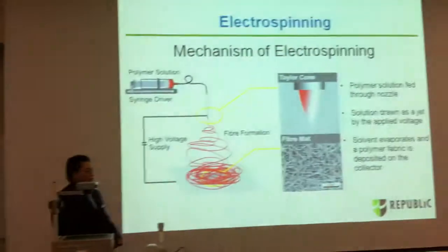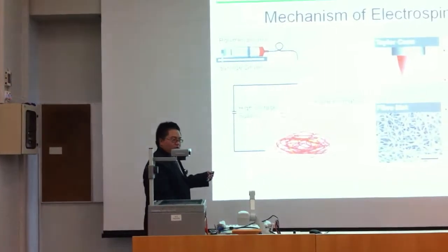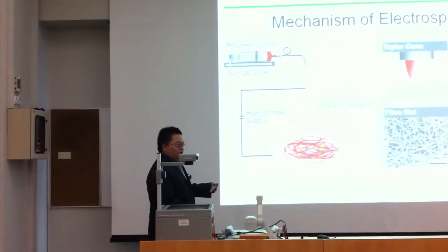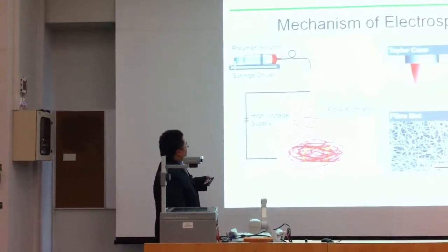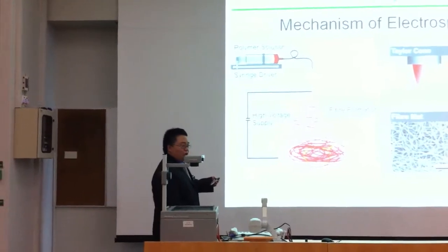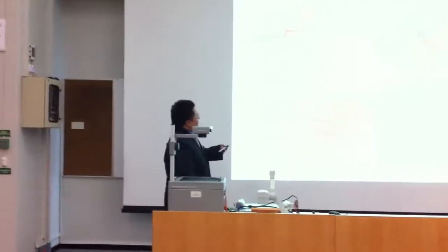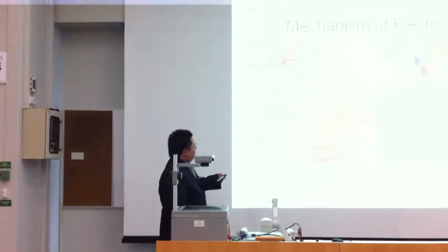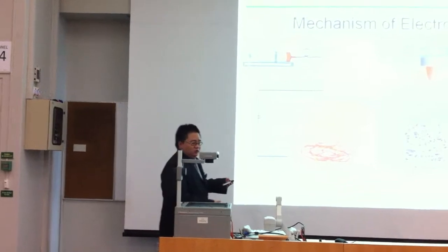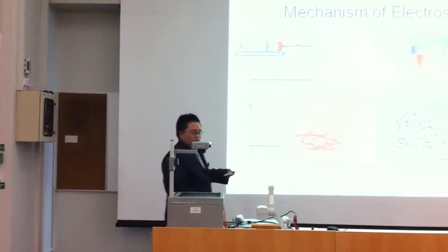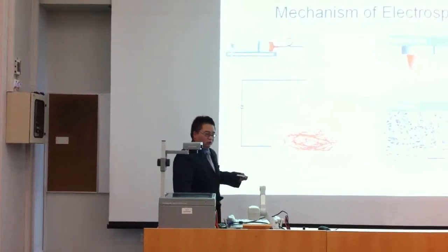So the mechanism of electrospinning. So firstly, polymer solution, which is the combination of a polymer resin and a solvent. And then the solvent has to be a dissolving solvent and a conducting solvent. So the polymer solution will be eluted out from the nozzle here, which will then be subjected to an electric field of any driving voltage, of which after elution, the solvent itself will evaporate from the polymer jet and then drying, in which the ions of the conducting solvent will then migrate to the surface of the polymer fiber, thus being stretched across and then being deposited onto the collector.